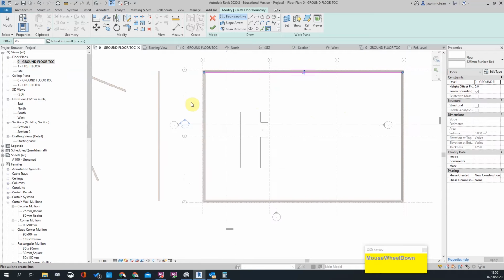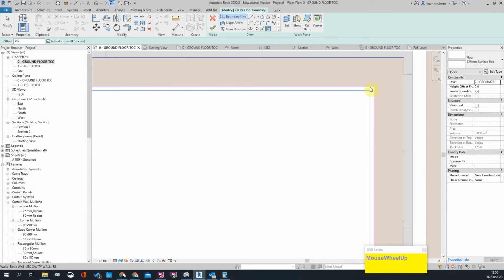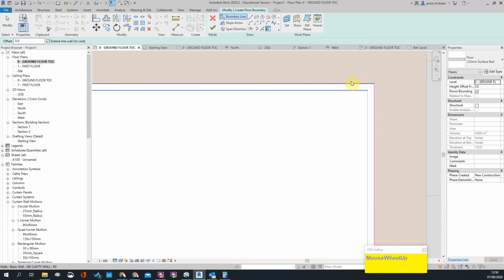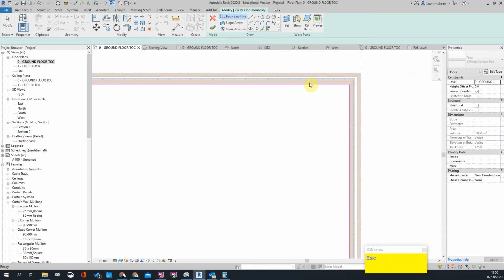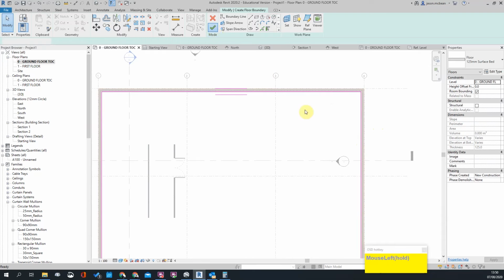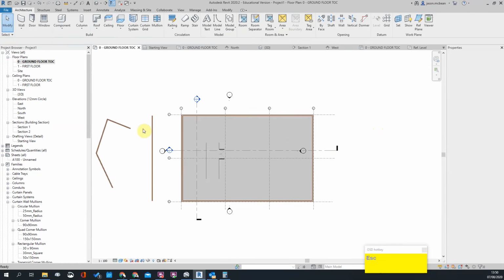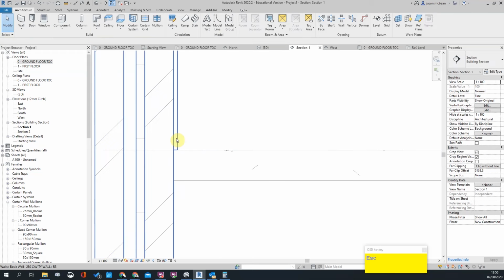Now you'll see it will either pick the internal core face or the external, and this is why you need to determine what the core layer is. And you'll see that it goes past the plaster into the walls, which is what you want. Okay, you can set an offset for this. So for your surface bed, I'm happy with that, for example. So here you see your surface bed will meet the wall and go past your core, for example.